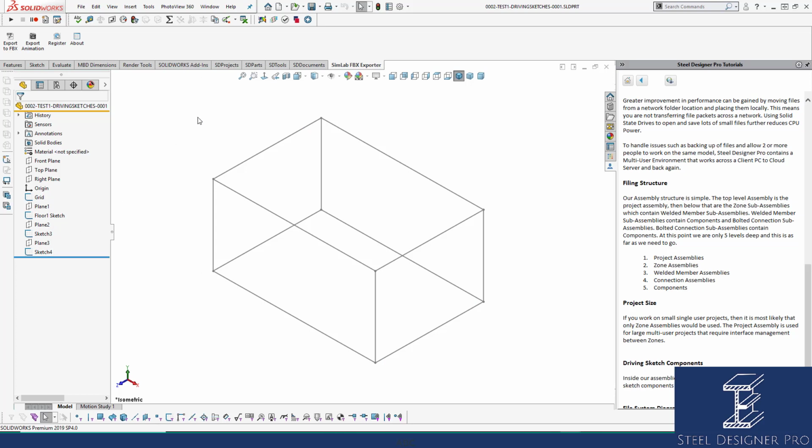We, through experience, have been using SolidWorks for over 20-something years now. I think since 1997 when it first came out. I was right there on the forefront of using it. I must admit that it's evolved over the years. And back then 3D sketches were common. We used to use 3D sketches a lot, and we found them to be a little bit unstable, but we've always gone back to, for some particular reason, 2D sketches on planes. It's because we can switch our sketches from one plane to the other. It gives us that flexibility to be able to do that if need be.